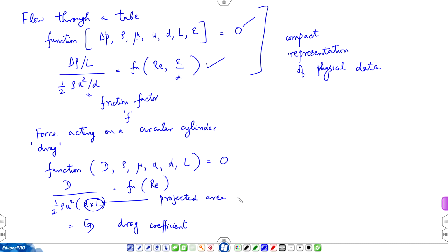It says there is a tube containing oil and it is partly filled, and you have to find, given the inclination, the flow rate. There you can find the friction factor by working with hydraulic diameter.